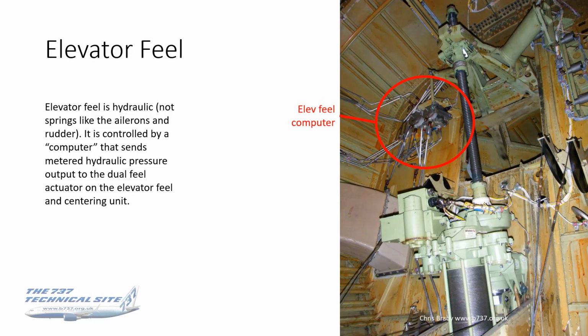Now, elevator feel, unlike the aileron feel and the rudder feel, which is done with springs, is hydraulic, and it's controlled by a computer. Now, this computer is not the sort of computer that you'll find in the E&E bay.